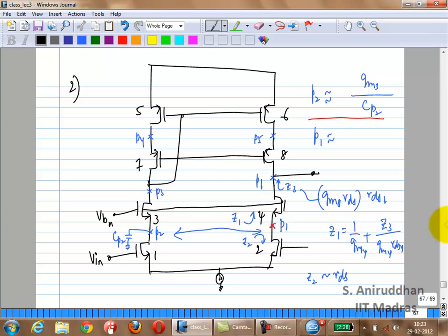Let's say you have an NMOS input path. You add an NMOS cascode on top of it, which reuses the same current, and you get a larger output impedance. You can replace this NMOS with a PMOS. Right? So in other words, how do you replace it with a PMOS? You need to be going into the source of a PMOS. Right? In which case, you can't do it this way. You need to fold it down. That's why it's called a folded cascode.